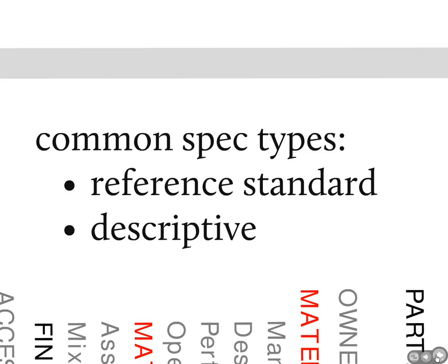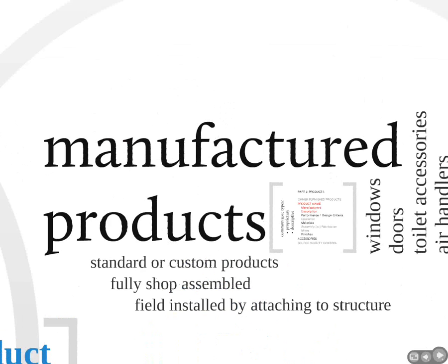Well, I was telling David that for many years on my gypsum board section, I put under submittals not required, because I just really don't need to spend time looking at product data for ordinary gypsum board or even Type X. Nowadays, of course, with abuse resistant and abrasion resistant and other types, it's a little more complicated, but we can still pretend it's not. Depending upon the project, yeah.